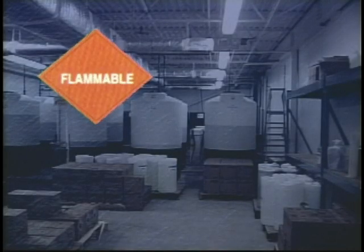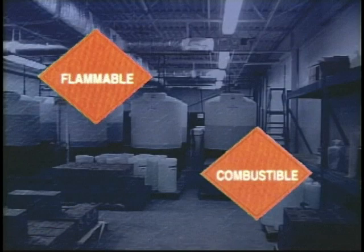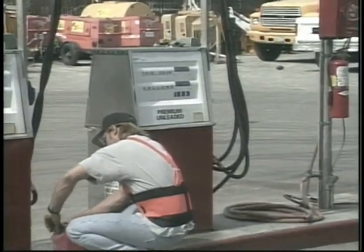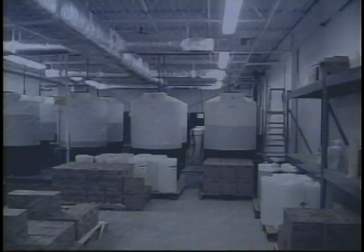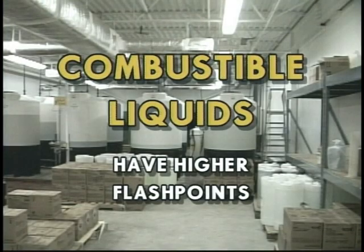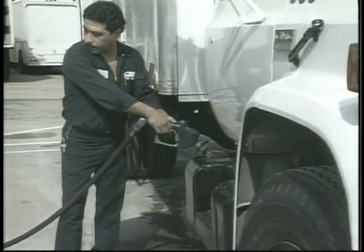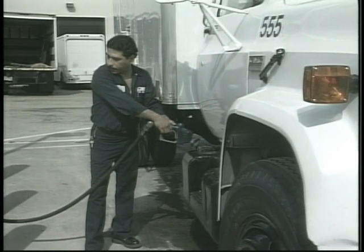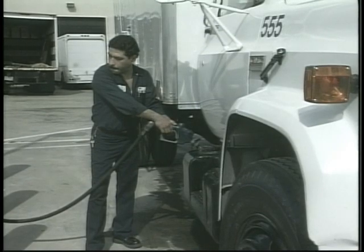Two of the more commonly labeled materials in the workplace will be flammables and combustibles. But what's the difference between the two materials? Flammable means the chemical, such as gasoline, has a low flash point and can be ignited quite easily. Combustible means that the chemical, such as diesel fuel, can be ignited, but at a higher flash point. Don't worry about the definitions of flash point, but flammables can be ignited more easily than combustibles.